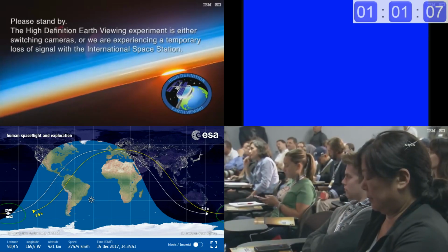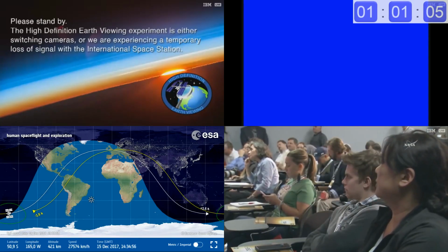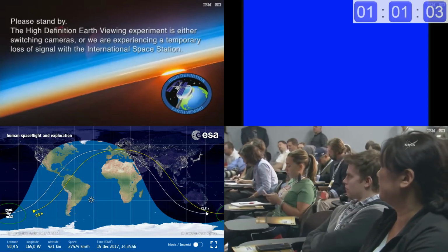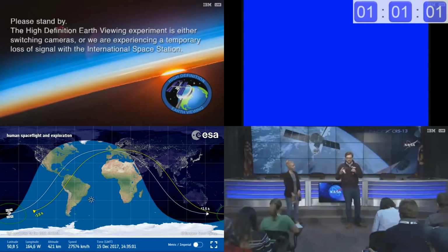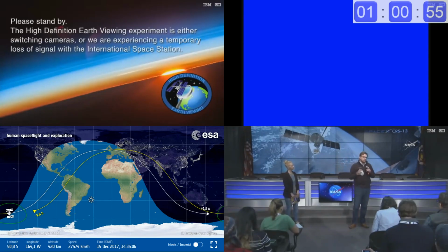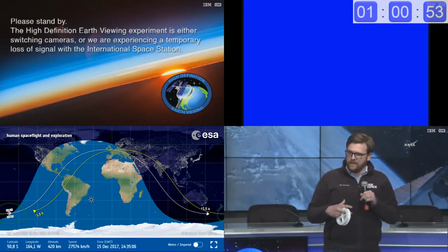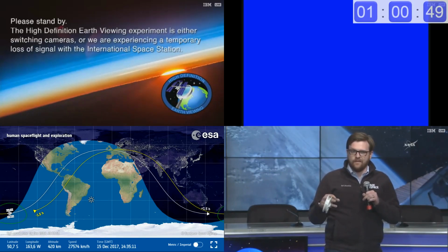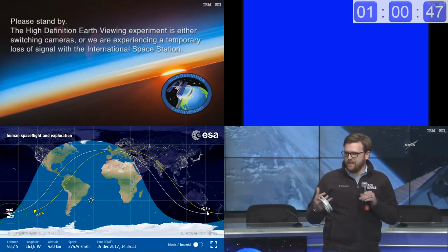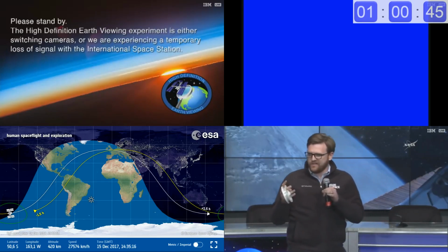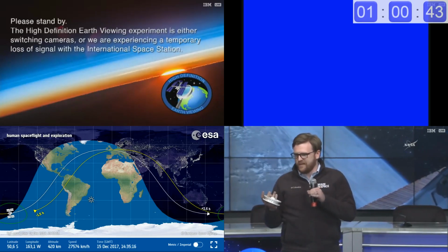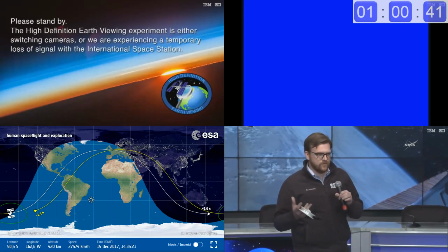Well, Z-band optical fiber, when it's manufactured in space, is potentially able to achieve this transmission spectrum that we're talking about. When you manufacture it on the ground, it turns out that there are these microcrystals that form in the fiber that ruin the signal transmission. Each one of these little microcrystals, at each domain, you lose like 4% of the light, and that just completely ruins your signal transmission.